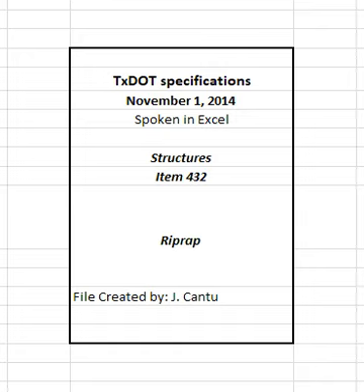Place stones to create a uniform finished top surface. Do not exceed a 6 inches variation between the tops of adjacent stones. Replace, embed deeper, or chip away stones that project more than the allowable amount above the finished surface. Prevent earth, sand, or foreign material from filling the spaces between the stones when the plans require Type R stone riprap to be grouted. Wet the stones thoroughly after they are in place, fill the spaces between the stones with grout, and pack. Sweep the surface of the riprap with a stiff broom after grouting.